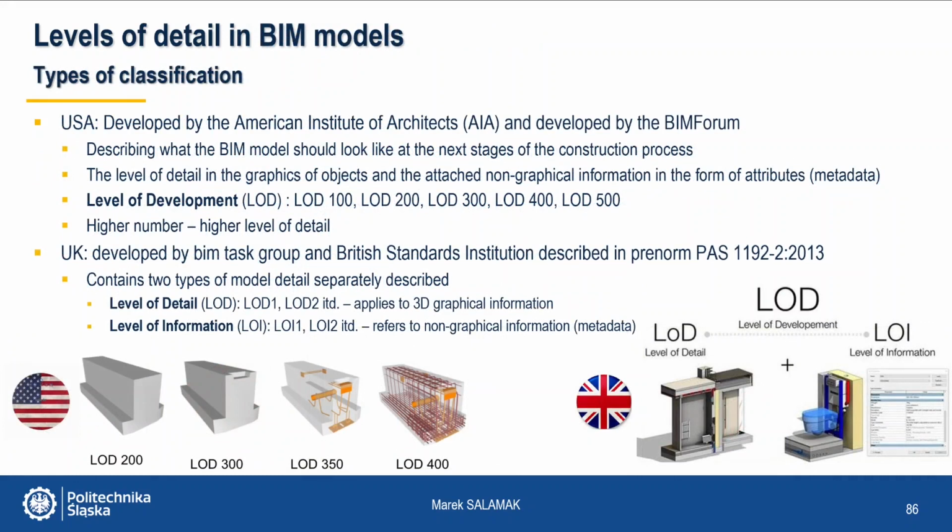There are two ways of describing the details of models in the world. In the United States, the term LOD is used, an abbreviation of level of development, with examples like LOD 100, LOD 200, etc. It was originally developed by the American Institute of Architects and is currently being developed by the BIM Forum.